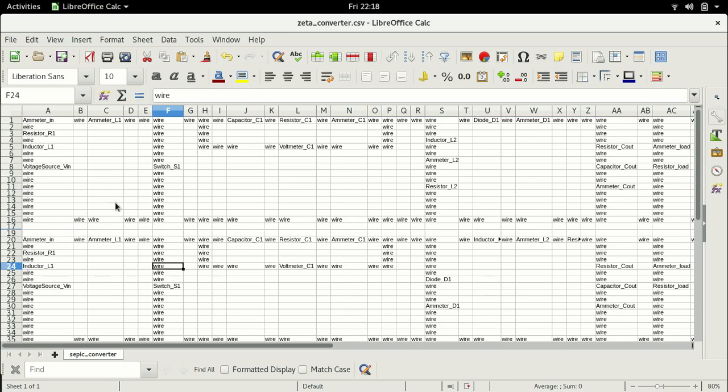Now that we place these two converters one above the other, the top one is the SEPIC and the bottom one is the Cuk. So let us compare these two and try to figure out where the ZETA comes in. Now, in the case of a SEPIC, we already saw that when the switch is turned on, at least I would say that both the SEPIC and the Cuk have the first stage common, right? Matter of fact, until the decoupling capacitor, they are common. It only changes afterwards, right?